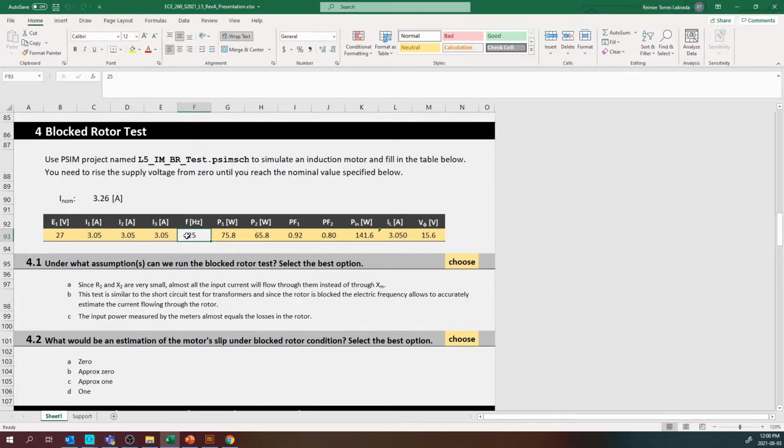Because this is not a transformer, it's a motor, a different machine, you choose this frequency depending on the class of the motor. We're using a class A, so just go read the book. It's very clear on why we do this. But you need to know that this test is run at 25 hertz because you're going to use that frequency in future calculations down the road.